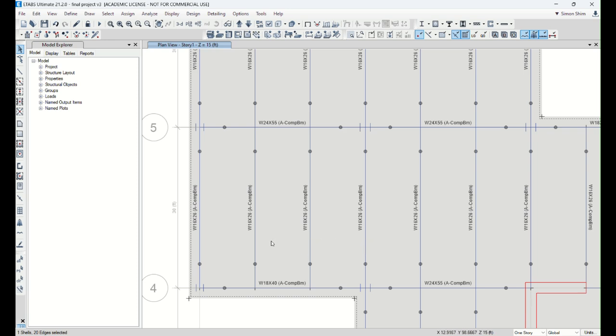First of all, I want you to just go through the first design, and see which ones have the same demands. The infill beams have the same demands, right? Because they are at 10 feet on center and 30 feet span. So most likely you need to come up with the same size. Sometimes ETABS gives you a different size. That means you think everything is perfectly 10 feet, but you may be slightly off here and there. Graphically, you may have drawn it that way. That's why sometimes ETABS gives you a similar but different size.